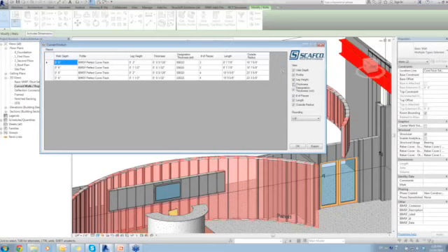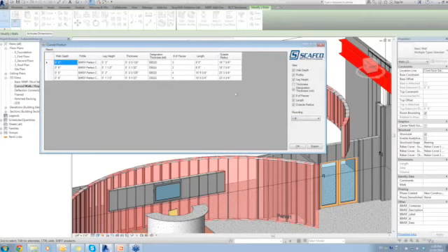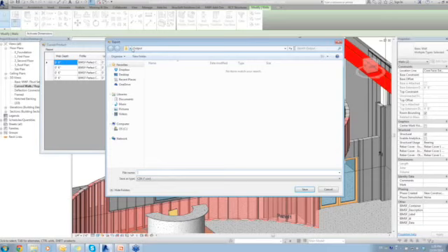I have the option to turn off columns that I don't need. So I don't need that, where's that thickness right here. If this is how I want my report to look, well, I can also change my rounding depending on how precise I want to be with my outside radius and my length. I can then export this information to this output folder I have created.